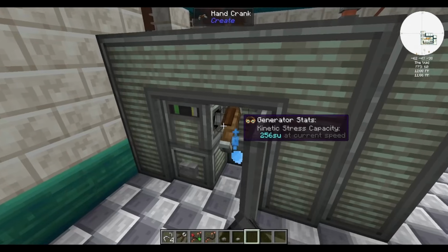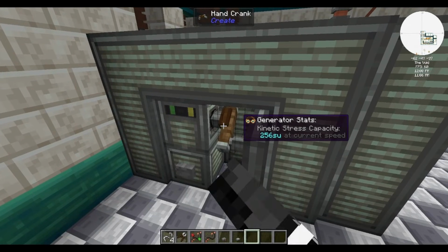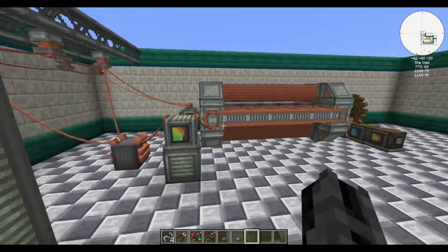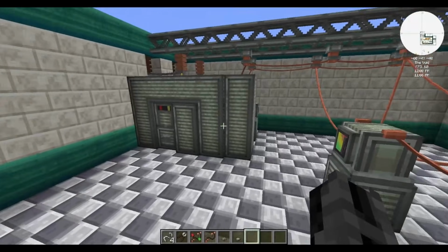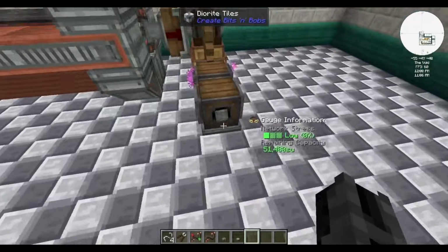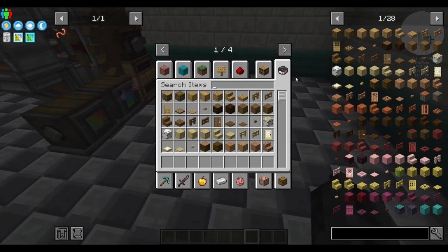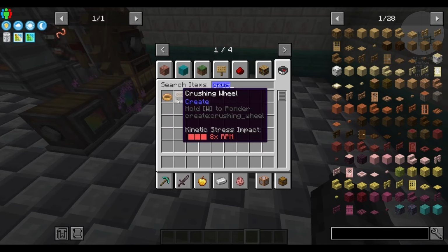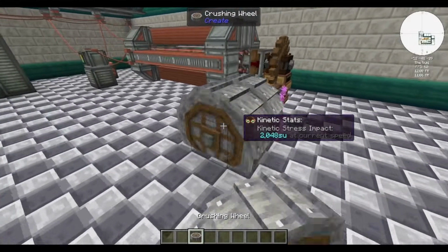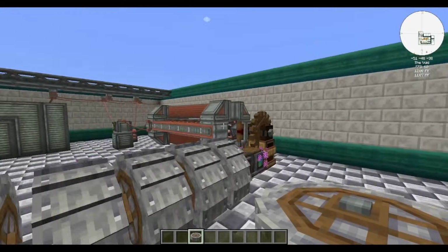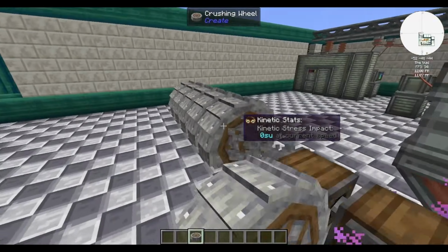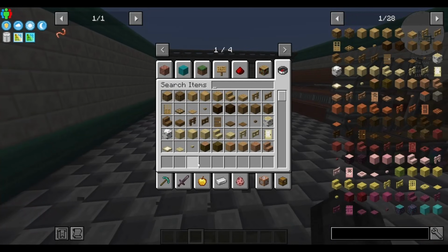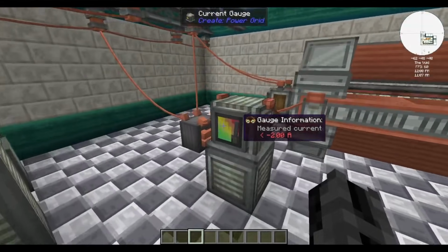So let me show you this example of a motor. Again, it has a breaker and its own transformer. It takes more current to spin up, then it goes down, and then the current becomes dependent on the load you put on it. Meaning the more load, the more current, and it slows down as you can hear. So yeah, these are the motors. Same construction, same rules with saturation.